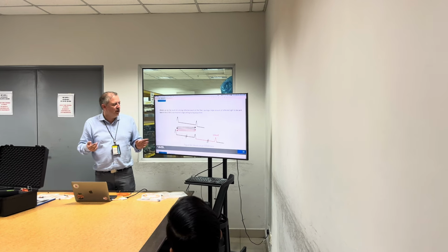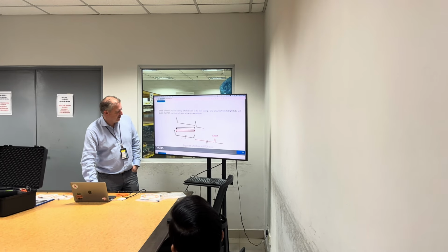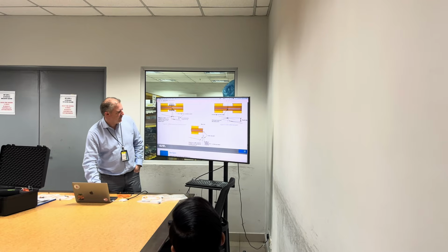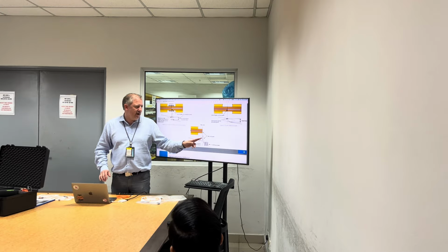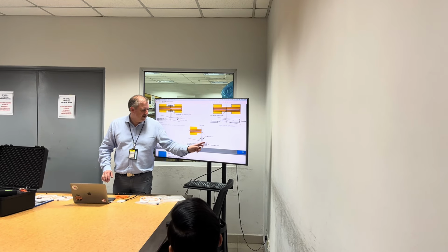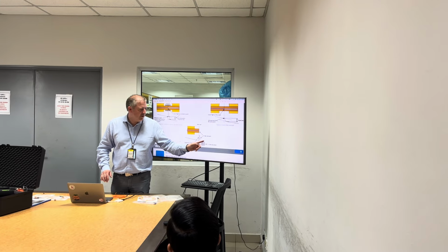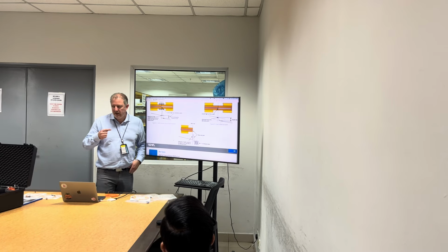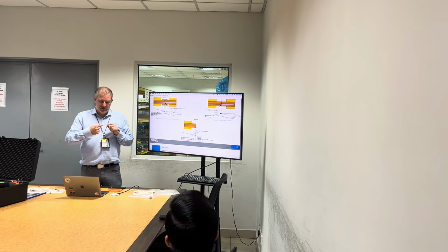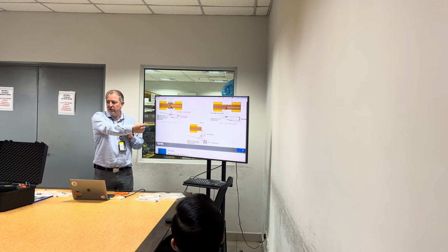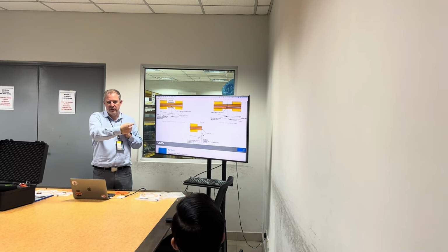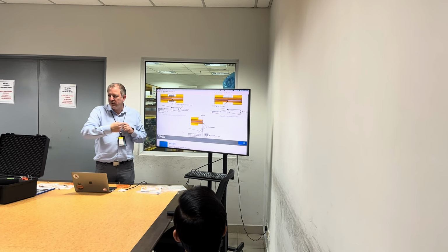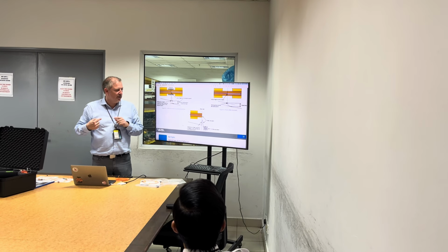So just so you know, sometimes you see this case. Sometimes you have the end of fiber and noise, and sometimes you can see one peak right in the middle of the noise. It's because maybe the light went through the fiber, you had a full reflection, it's coming back, and you have another fault. It goes back again in the other direction and comes back to the meter.